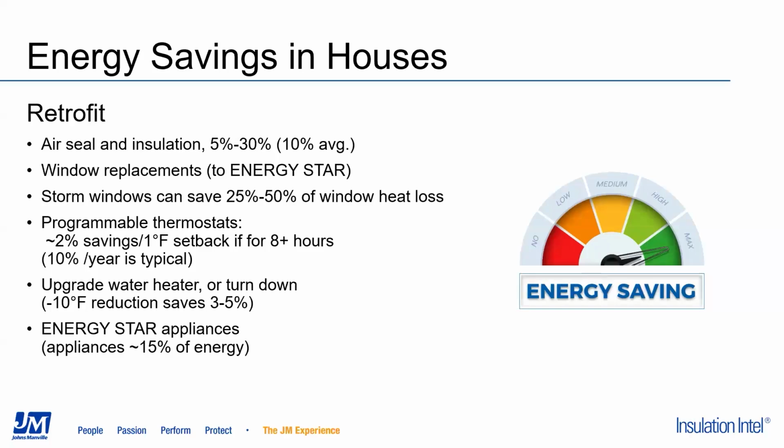But again, not only do we save energy, it makes a dramatic improvement in the comfort of our homes. Window replacements, whenever that needs to happen, upgrading to double pane Energy Star windows, or better yet, triple pane, can realize good savings. Just adding things like storm windows can save a bunch off of the heat loss through our windows.